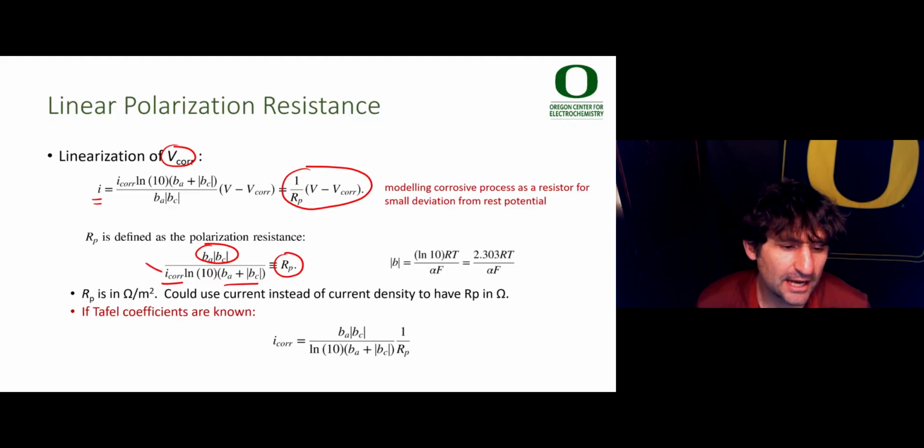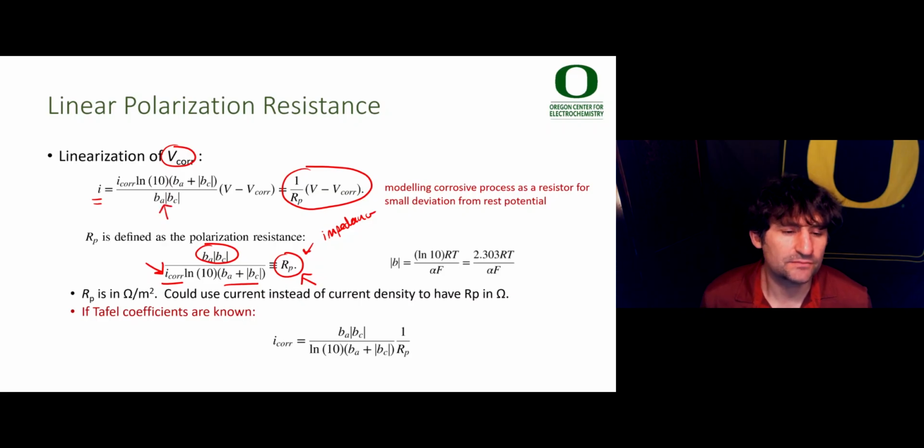You can see here that as I corrosion increases, the polarization resistance due to corrosion goes down. This is what you'd measure with impedance, for example. You could measure this polarization resistance directly, or you could do a very small sweep in a current-voltage curve and get the slope to assess this polarization resistance.